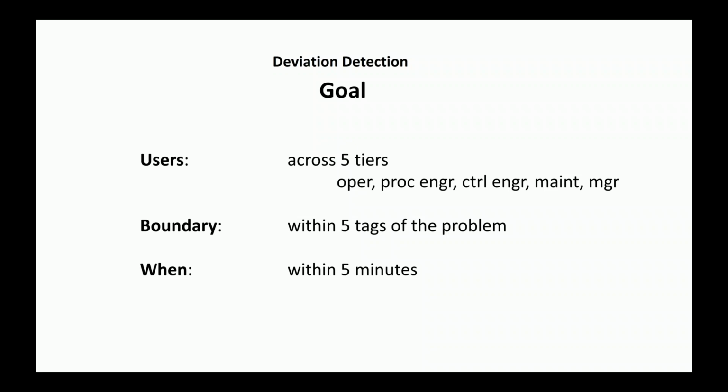The tag browser is great for saying, okay, under the tag name, you type 1.1 and then star.pv or something like that, because the PVs are generally the ones you're after. If they're categorizing the plant that way, in a very short time, in 15 minutes, you can be up and running with a list of tags to get you a long ways down the road.